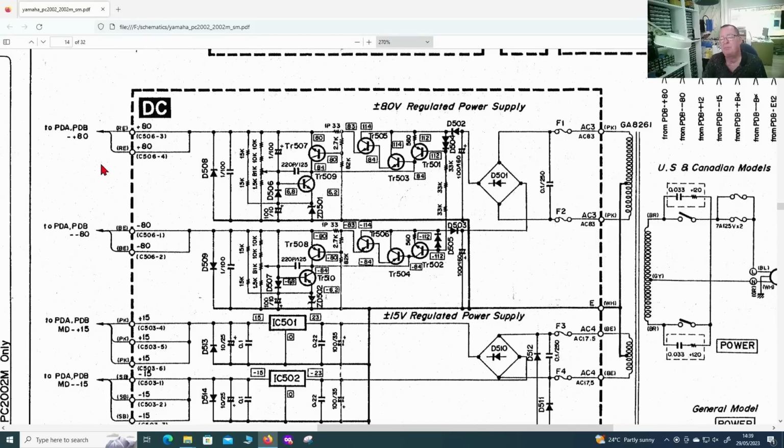And you are right, but what you also need to consider is the voltage on this rail. If this was a 10 volt supply, 80 ohms, you'd have an eighth, about 125 milliamps flowing into that short, which isn't a short. But with a plus 80 volt rail, 80 ohms or a bit less, you've got 1 amp or a bit more. So you're now drawing an amp from here. Now, even 1 amp might not sound that much. But at 80 volts, 1 amp, well, watts is volts times amps. So that's 80 times 1 is 80 watts. Yeah, so that's a lot of power.